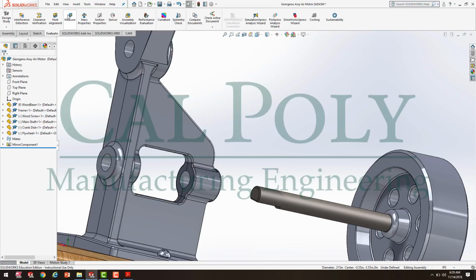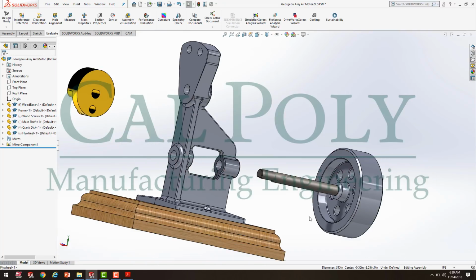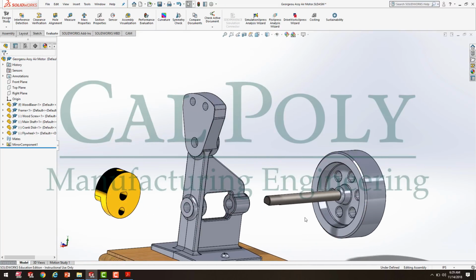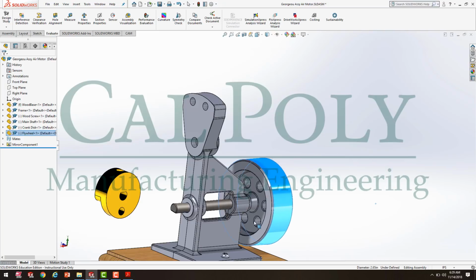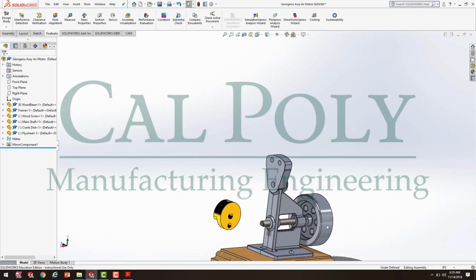Press escape to cancel. So we hit measure. We can go from here to there, and it's 2.48. So if you look, we have about 30 thou difference right there. So we have 30 thou, so we're going to have 15 thou offset. So what I can do is set up a relationship that allows it to shift back and forth about 15 thou between the surfaces.